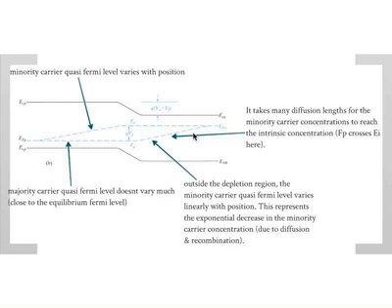You can have a situation where the injection is so high, but still lower than the majority carrier concentration, that the minority carrier concentration could be higher than the intrinsic carrier concentration. That's the regime of high current injection, and it's typically how it's operated. Do you see what that means? It means that you have a pretty big jump in the minority carrier concentration pretty rapidly.